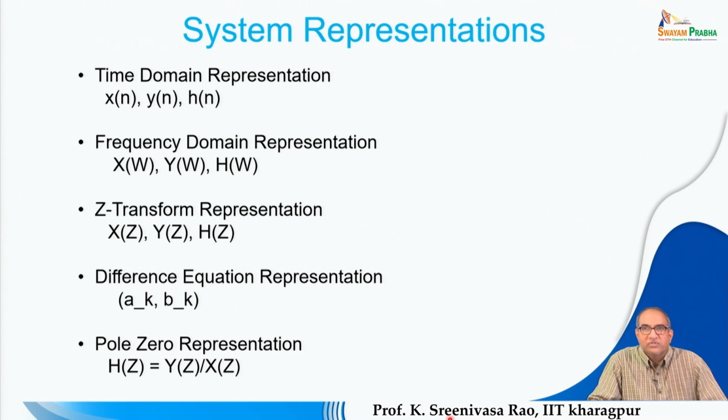For that we can use the Fourier transform, but as I mentioned, since we process these speech signals by machine, by a computer, it cannot handle analog signals. Therefore, we need to convert the signals to discrete, and afterwards quantize them. For analyzing the frequency domain, both the time domain signal as well as its spectrum should be available in discrete form, with finite duration and finite amplitudes. In view of that, the discrete Fourier transform will carry out the desired task of computing the